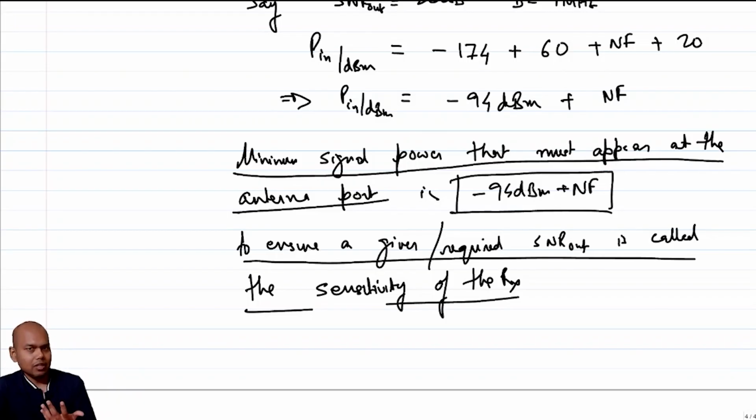Or in other words, from a very broad business perspective, if your noise figure is lower, you can get away with a smaller number of base stations. You need fewer antennas because your handsets are more capable of operating with smaller signal power. So noise figure has a very top-level, system-level importance. It directly relates to finances in some way.